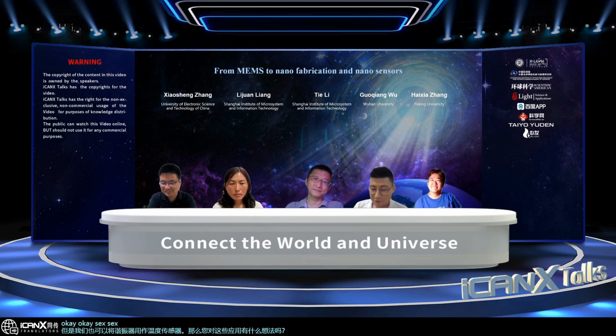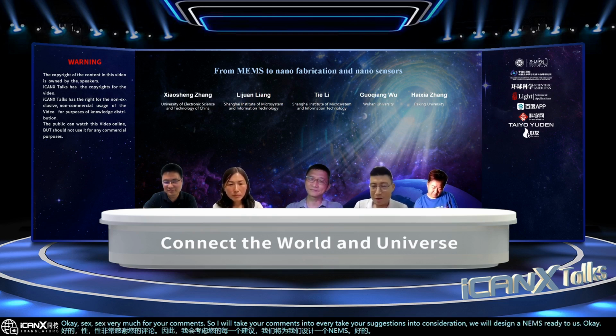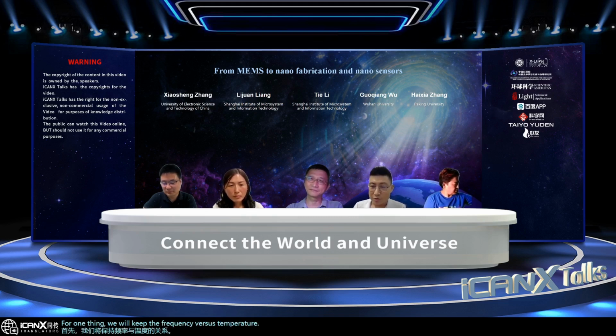Okay. Thanks very much for your comments. I will take your suggestions into consideration when we design the MEMS resonators. For your question, yes, we also have this for resonators. For one thing, we will keep the frequency versus temperature, the TCF, as small as possible. On the other hand, we can also use the frequency dependency on temperature as a temperature sensor.